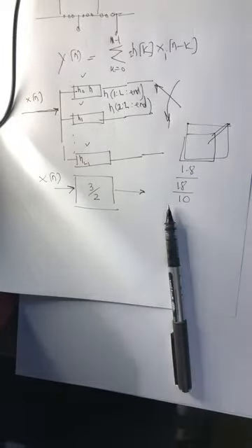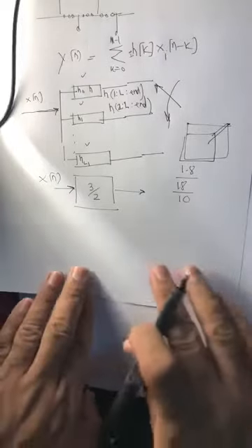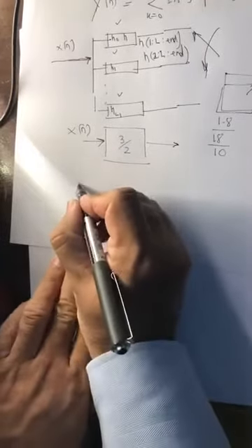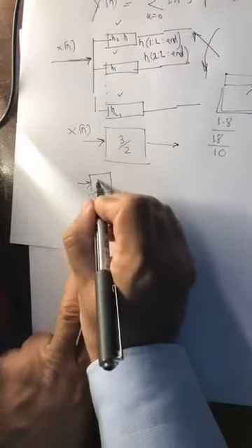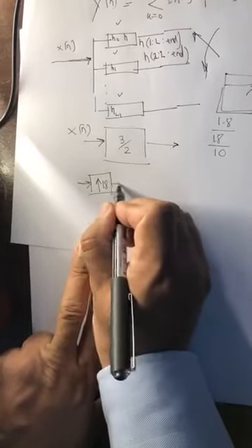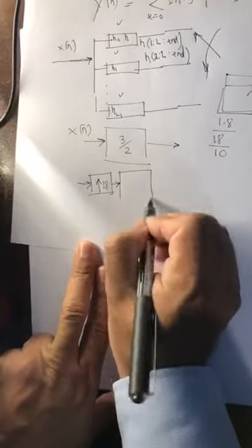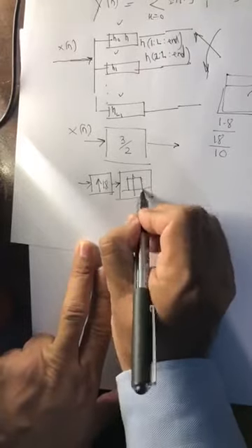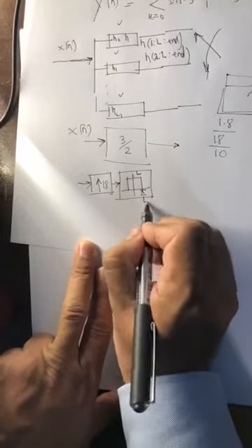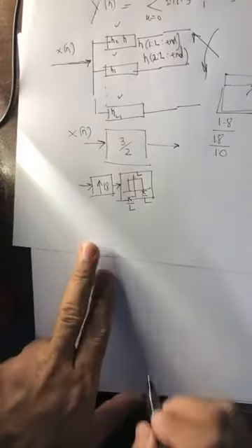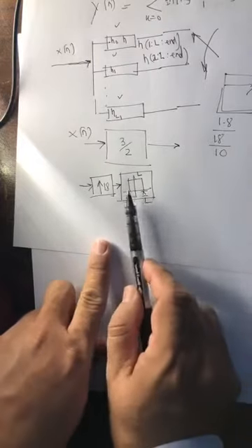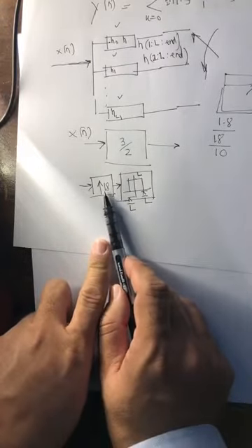One is, first increase the sampling rate by a factor of 18. So how do you increase the sampling rate by a factor of 18? We know this. First, insert zeros after every sample, 17 zeros. Then pass it through a pi over L filter, right? This will make your image 18 times bigger, though you are not displaying it, okay, because you want to display 1.8. So this will increase the size of the image by a factor of 18.